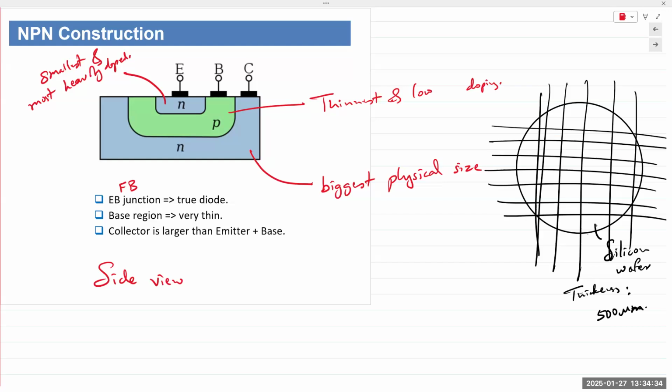And then since we are talking about the micro scale, we actually build from the top. We do surface micro machining. So mostly just X and Y direction. We simply use the top few microns out of those 500 microns of thickness of a wafer. We are simply using the top surface, meaning the top 1 or 2 microns. Okay, we are not even going into the Z direction. And the way it works is,